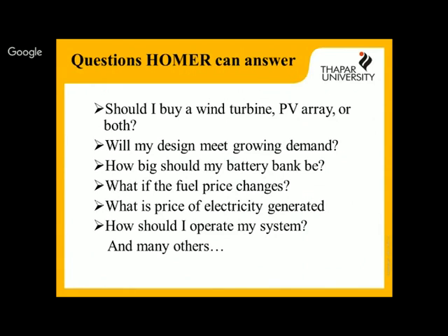Why am I saying that? Wind is economical and PV. Let's say you don't have plenty of wind resources available at your location. You have very poor wind speed. Then wind will be costly, because to operate a turbine we need a fixed amount of wind speed. And suppose you are going to put that wind turbine in this room, then this is totally a wastage of money.